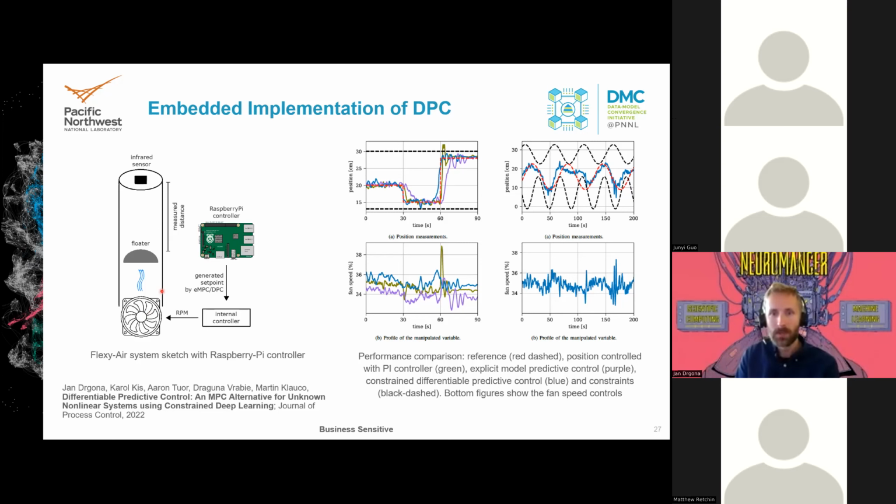We used the learned system model in the closed loop, we trained the control policy using these differentiable predictive control principles, and we shipped them the control policy, never seeing the system, and they deployed it on the Raspberry Pi and compared against MPC and PID. The results have been quite favorable in the sense that model predictive control is quite expensive. That's why they had to make some reductions in their problem complexity that hampered their performance. Because we pre-computed the solution offline and deployed only a neural network, we didn't have to do these simplifications, and we obtained better performance in terms of reference tracking.